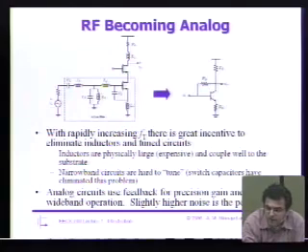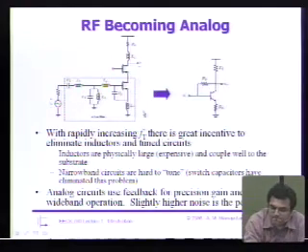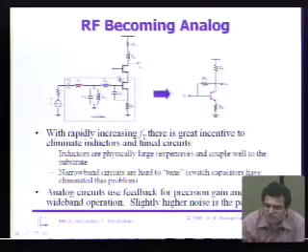The circuit on the left essentially is open loop. Now, it does use some local feedback. It has this degeneration inductance, so technically it also uses feedback. But if you vary the process or the temperature, the circuit on the left is going to vary a lot more than the circuit on the right. What's the price that we pay for using feedback in this particular example?